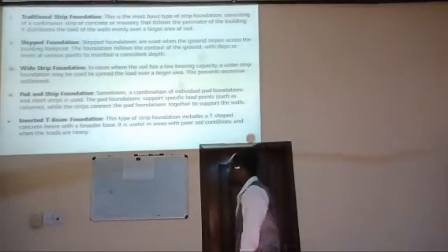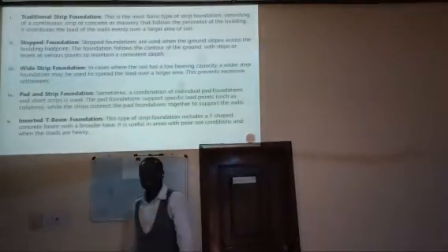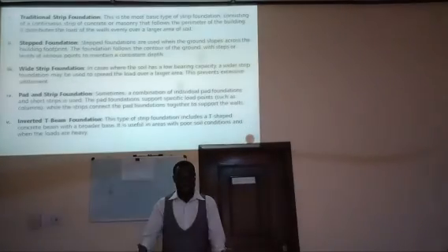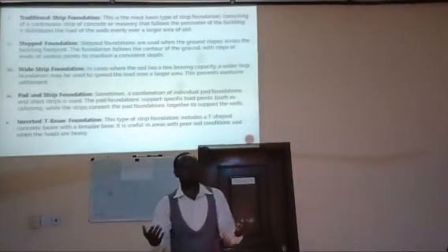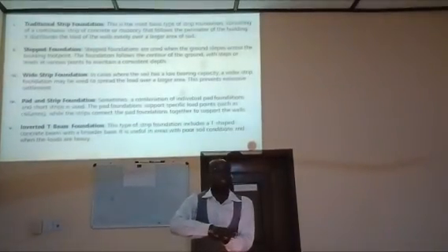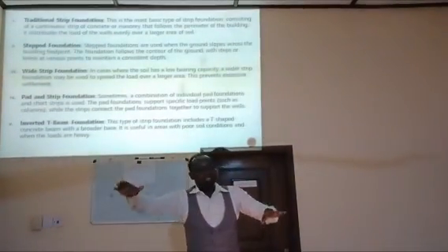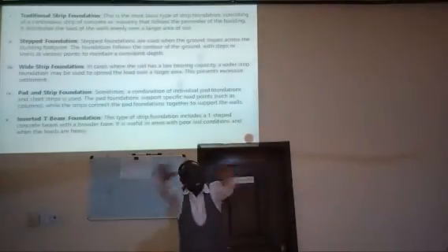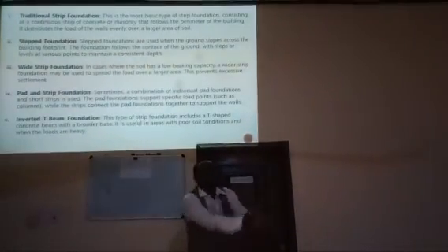Now, please next stage. What are the advantages of strip footing? Many of them: it is cost effective, you distribute the load evenly, it is suitable for various soil types. The construction is very simple, and then it has low maintenance after construction. And then please next slide.